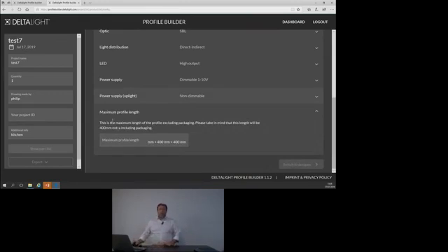The next question is now this maximum length for transport. So if I will make a construction, I can indicate here what is the maximum length of one individual part. If I say, okay, for transport and access to the building, the profile should not be longer than 3 meters, well, I write here 3 meters, so 3,000. Voila. Attention, there is an addition of 400 millimeters for packaging. So the maximum part will be indeed 3,000. There will be no length longer than 3,000.